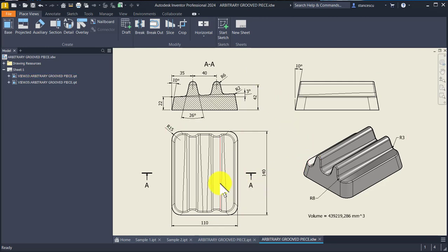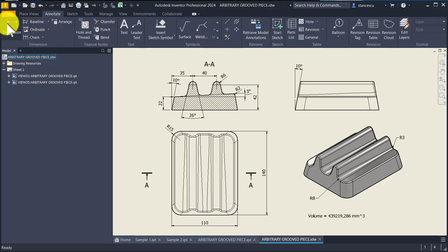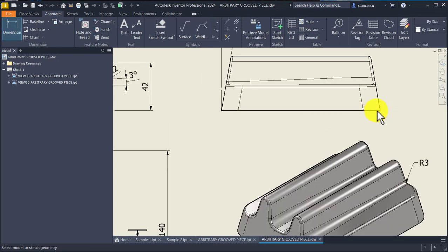We start with creating a parallelepiped pad with dimensions 110, 140, and a height of 42 plus 6. I will apply for you a new dimension here in order to have a general value for the height.